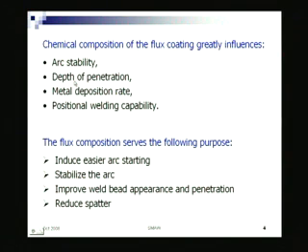Next thing, it influences the depth of penetration. Depth of penetration means you are striking the arc, and that heat, how much it is penetrating in the metal plate. How much it is penetrating in the metal plate means to what extent it is melting the plate, how much depth. That of course also will depend on the thermal conductivity of the plate material, but also will depend on the arc characteristics.